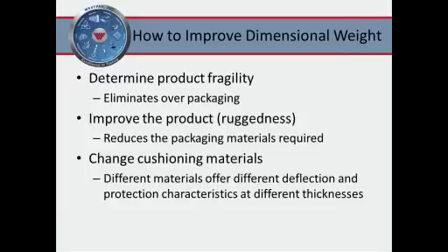What this means is that if you have a 2-inch thick polystyrene, you could deflect 1 inch before it becomes hard and useless, and it actually will damage your product because it's so hard. Secondly, the second type of material that I'll talk about is expanded polyethylene. Expanded polyethylene has a deflection percentage of around 70%. Because it deflects a lot more, with the same 2-inch piece of polyethylene you actually get to deflect 1.4 inches. So that's another way that you could cut down on the cube.